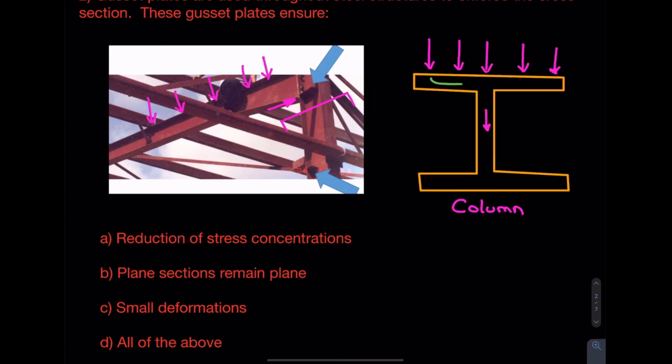well, if you guys assume that the path is going to go something like this, we're horribly mistaken. So the stress has a very hard time doing a path as such. And because of that, there will be a lot of stress concentrations around these two corners right here.